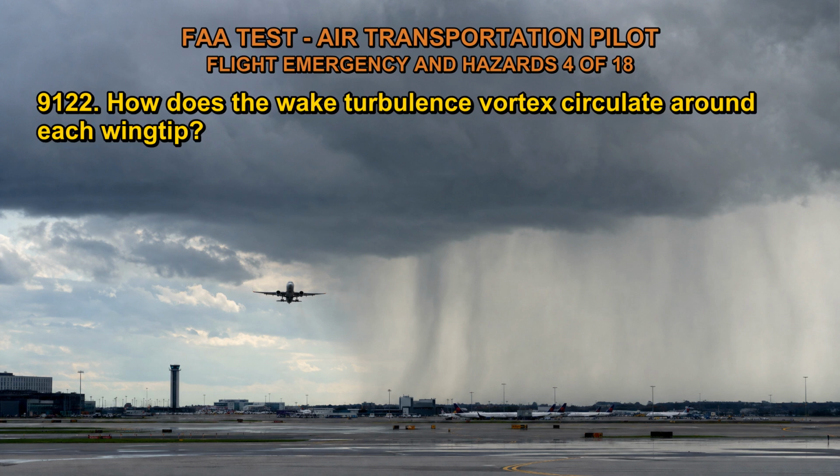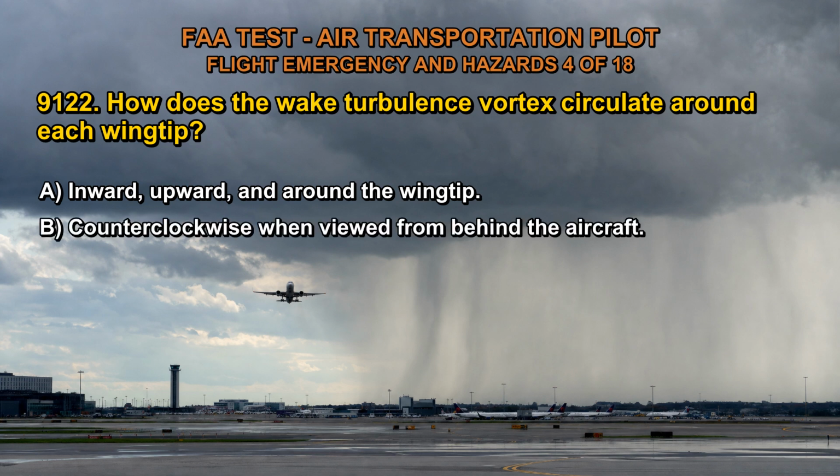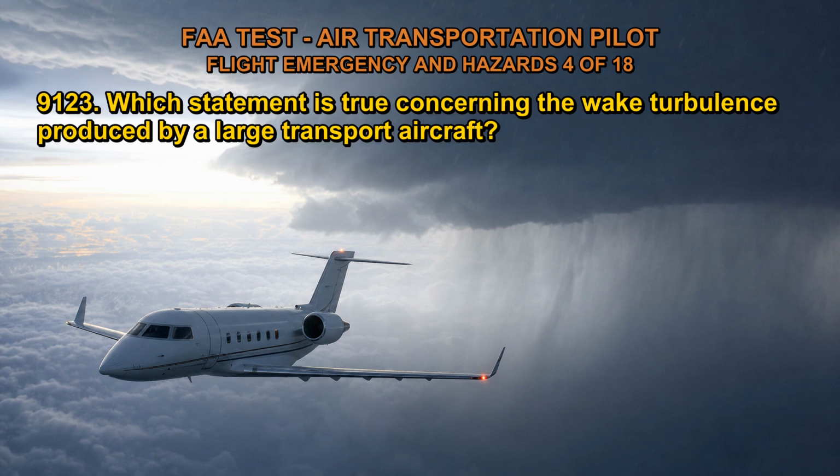9122. How does the wake-turbulence vortex circulate around each wingtip? A. Inward, upward, and around the wingtip. B. Counterclockwise when viewed from behind the aircraft. C. Outward, upward, and around the wingtip. The correct answer is C. When viewed from either in front of or behind the aircraft, the vortex circulation is outward, upward, and around the wingtips.